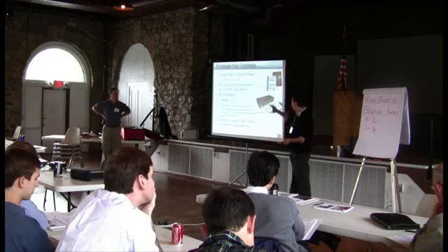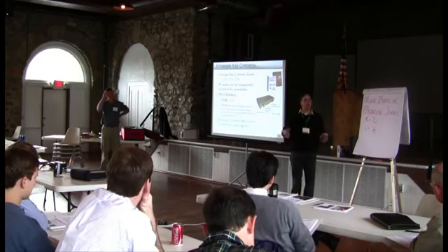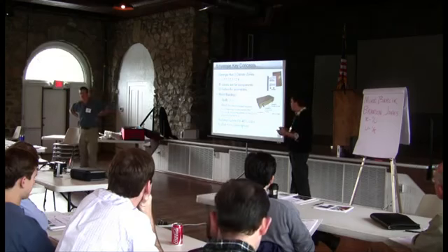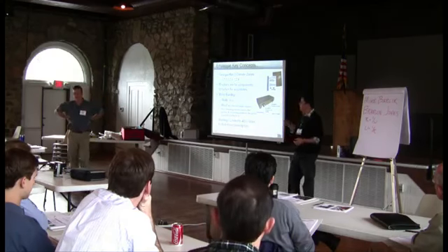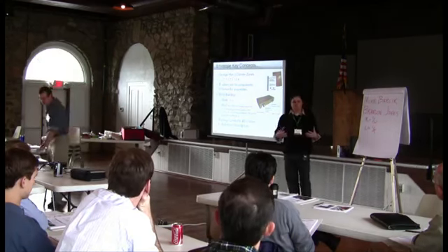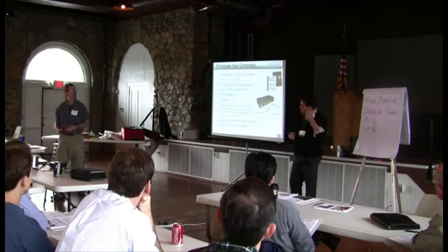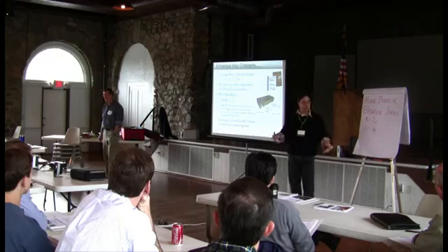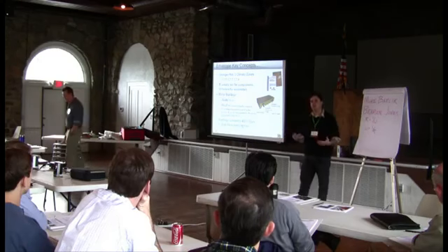So a piece of insulation will have an R value. It will be able to resist conduction by X amount. They use U factors or U values for assemblies. So take a window: it's multiple components. They do not talk about R values. They talk about U values.